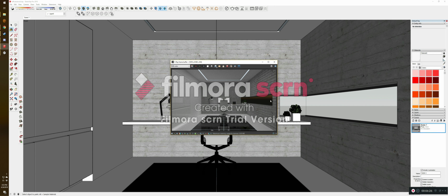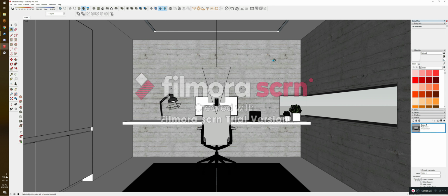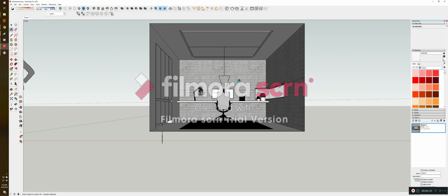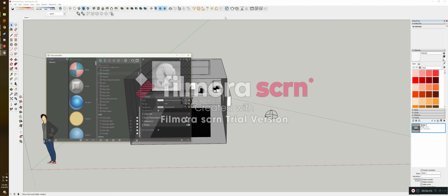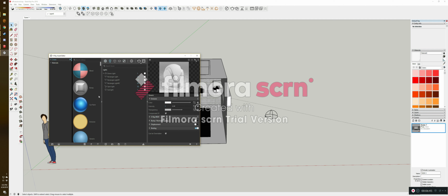The last thing I'm going to do is assign some exterior landscaping to this. So we'll X out of this, and to do that, the preferred way I like to do it is to input a dome light in the model. So I'll just have the dome light there, and we will go to our light settings, and the dome light is going to account for everything outside, so we can actually turn off the SketchUp sunlight by clicking that.